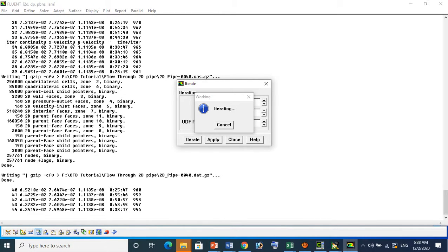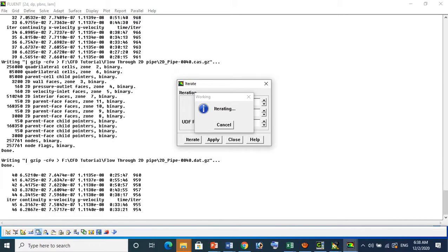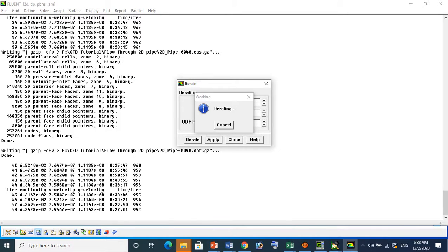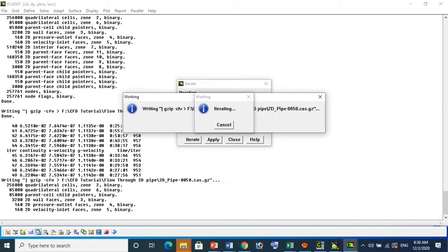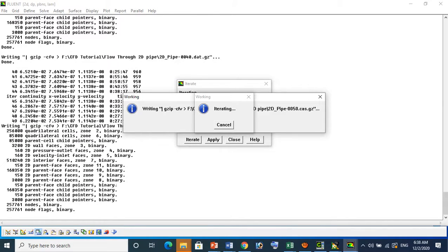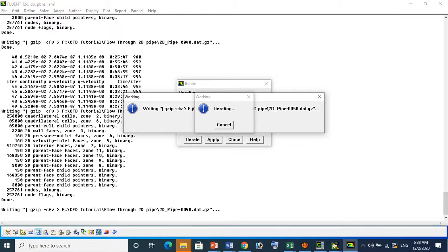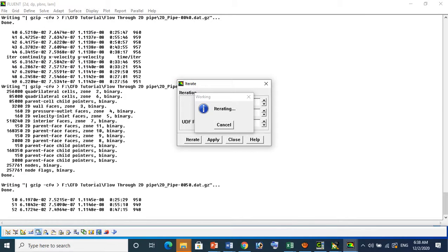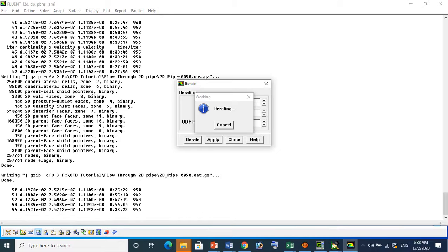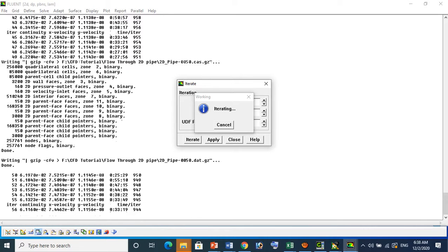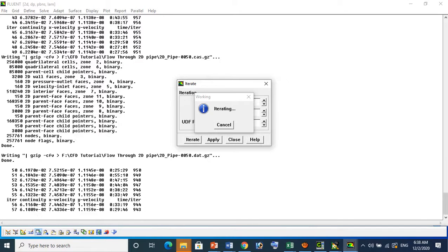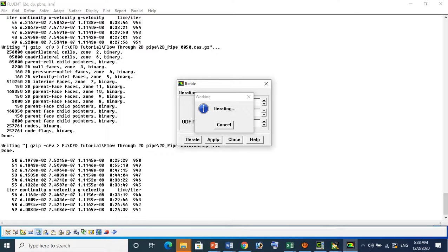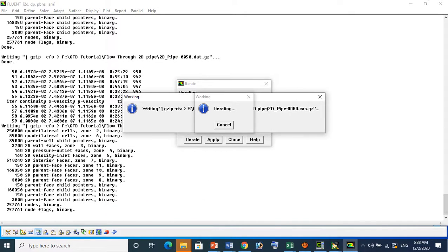Before that, I would like to give some important tips for numerical simulations. There are different parameters which affect numerical simulations, such as grid sizes, grid shapes, and proper boundary conditions. So we need to understand the physics of your problem clearly to get accurate and faster results.